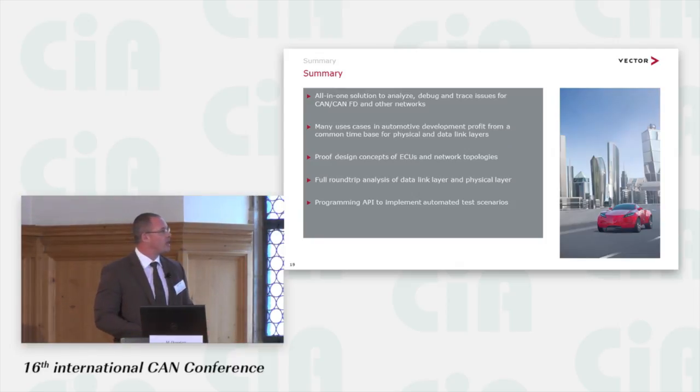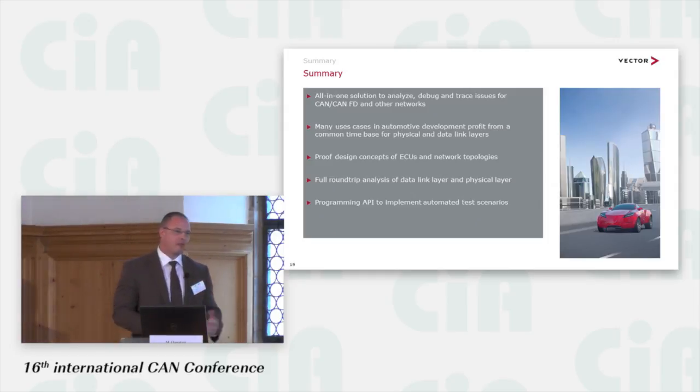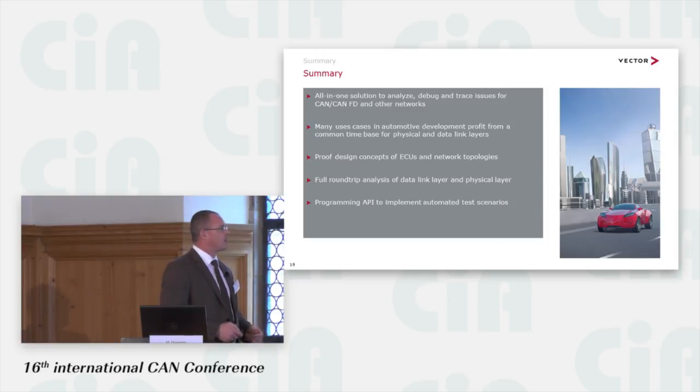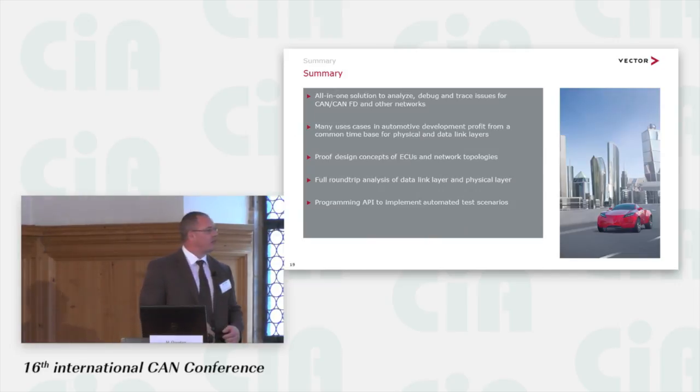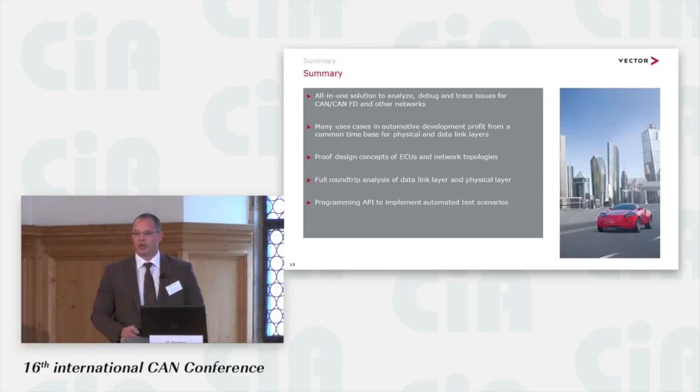You can prove your design concepts for ECUs or for different bus topologies. And you can perform a full round-trip analysis through all layers, starting at the data link layer, coming to the frame layer, then to the bit layer and back. And you also have the possibility to establish your own test scenarios running in a loop with a high degree of scalability and reproducibility.